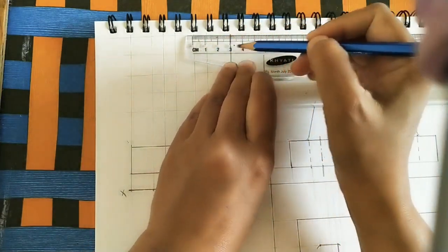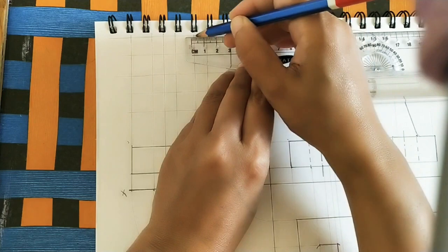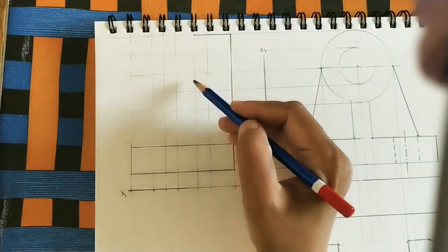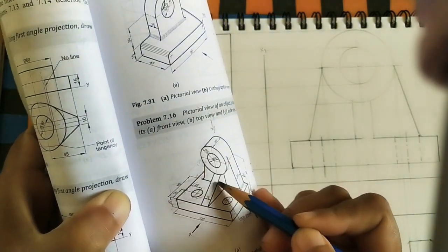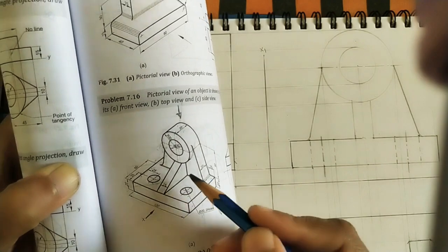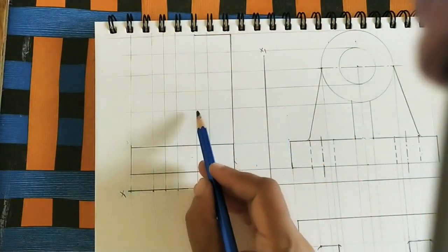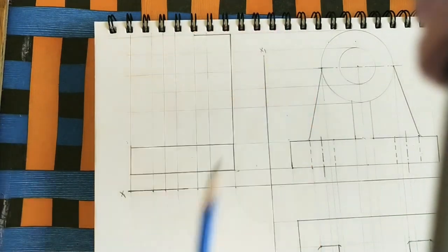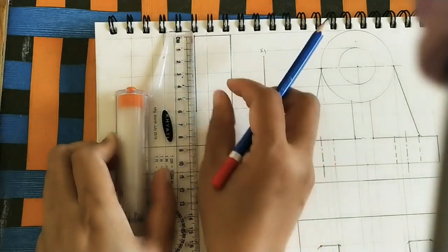If you measure here, we can get the 30 mm here also. But every time there is no need to measure. Just by seeing the projector line, we can get the 30 mm here. After that, how much length can we see? Whatever this diameter is here, up to the diameter we can see this thickness, from the side view. So here the diameter we took up to this. From this projector line we can take here. Just make one dark line up to this. So this thickness we can see from the side. From this point we can see the dark line thickness.